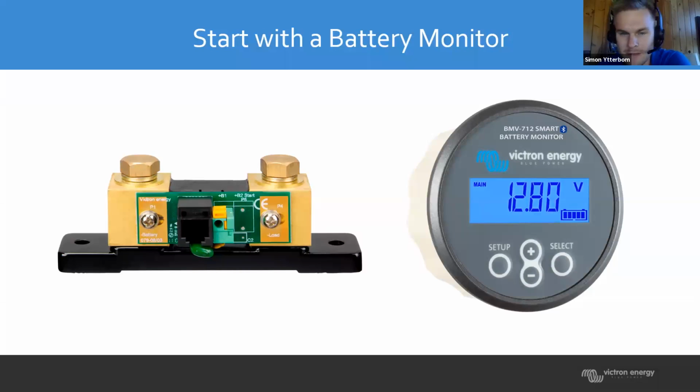for your specific battery bank. For example, if you're just using a voltmeter, the volts will fluctuate depending on the load that you have on the battery. A starting battery in a car, for example, we know the battery is fully charged. We've been driving for a while, but when we're going out to start the engine, we know the battery voltage will drop down to, let's say, 10 volts.